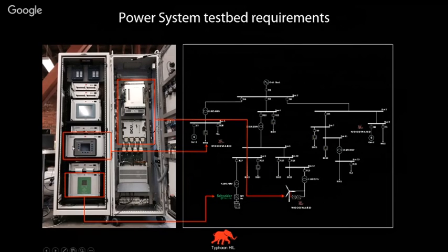But in order to connect real control of a genset, of a diesel generator, or of a solar inverter or an active filter, we need to embed the real controllers. To connect them to this kind of simulation, these parts of the network that are controlled by real controllers have to be simulated in a much smaller time step with much bigger dynamics.